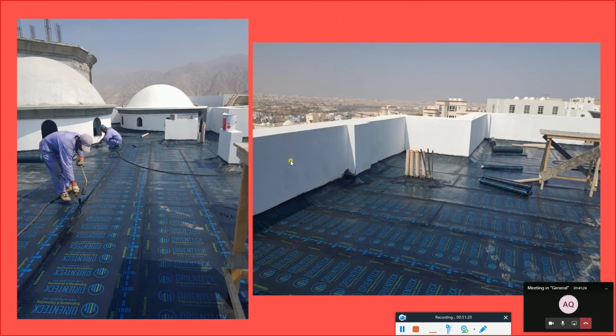Waterproofing, this is going to be for the roof now. Okay. For the roof, to ensure that you will not have any issues with water leaking and causing you issues for the reinforcement, in case of rain or any other things, it's better to make a waterproofing. And once again, they are using bitumen here, and this bitumen is applied using fire. Okay, so they are using the heat of the fire in order to stick this particular bitumen.